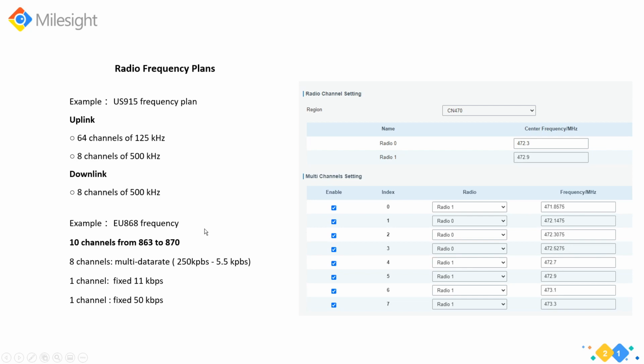And since LoRa works in the unlicensed spectrum, everyone can set up a LoRa gateway. Everyone can deploy LoRa sensors in the field and receive LoRaWAN traffic. In the LoRaWAN protocol, for the frequency bands, US915, AU915, or CN470, everyone can pick from those authorized frequencies and set them up in the Milesight gateway and end device to receive and send packets. But the channels, the frequencies, are really close to each other.